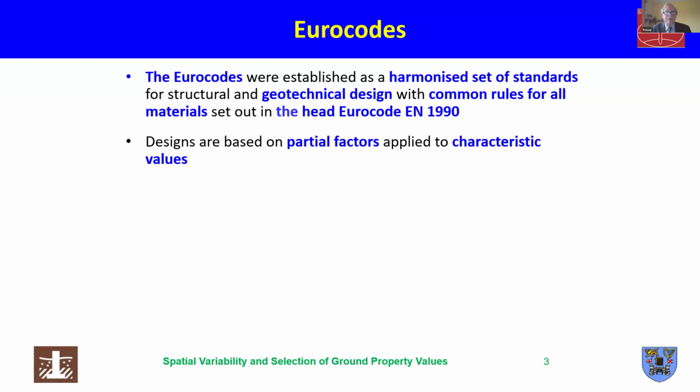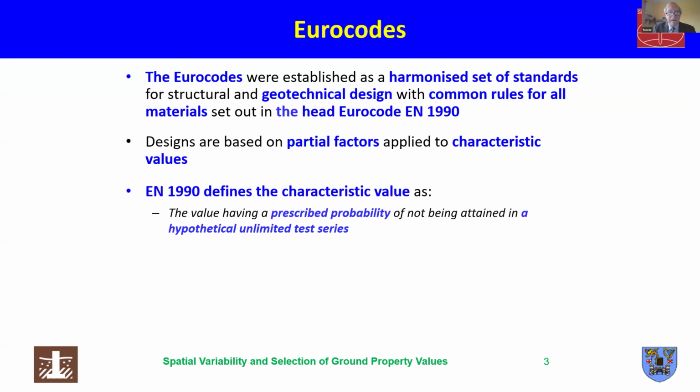And designs are based on partial factors applied to characteristic values. And EN 1990 defines the characteristic value as the value having a prescribed probability of not being attained in a hypothetical unlimited test series.